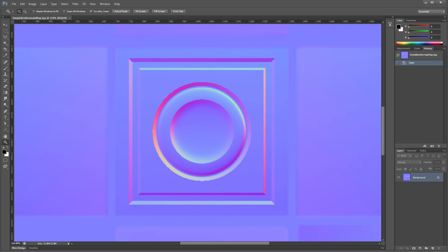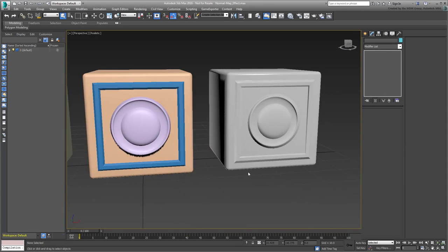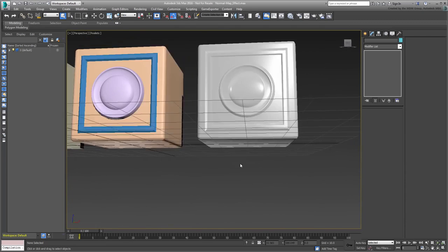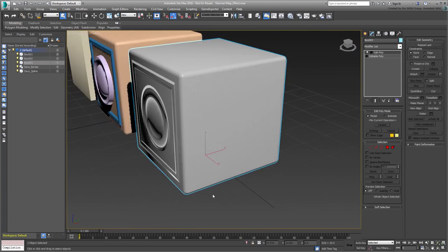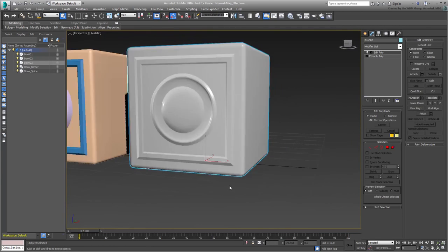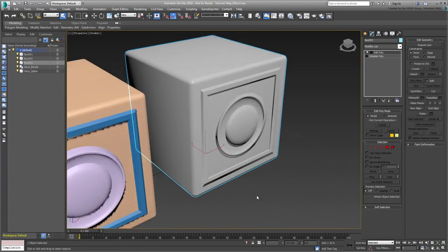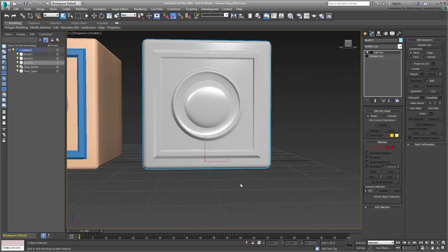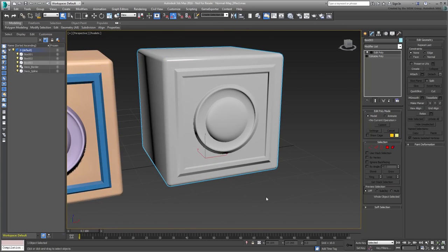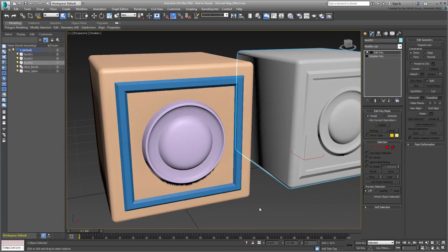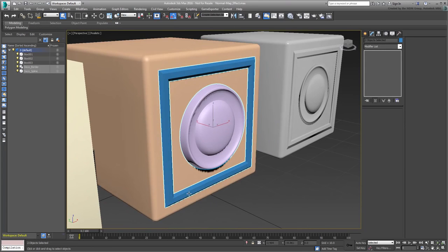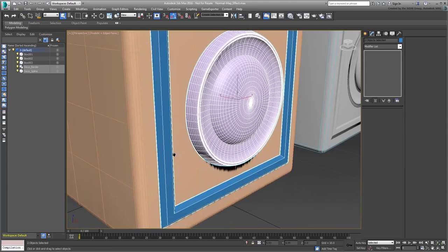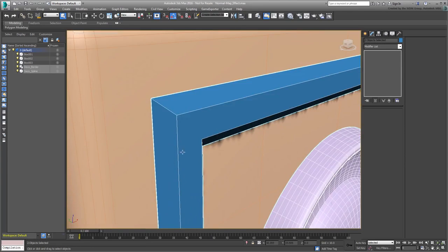Be aware that the viewing angle is important, and the model can look perfect from one angle and less than perfect from another. Viewing the front from a parallel angle doesn't have the same effect as from a perpendicular one. You'll also notice that the detail elements were all curved or beveled. This is important, as you want to prevent any geometry that has parallel faces to the normal map projection.